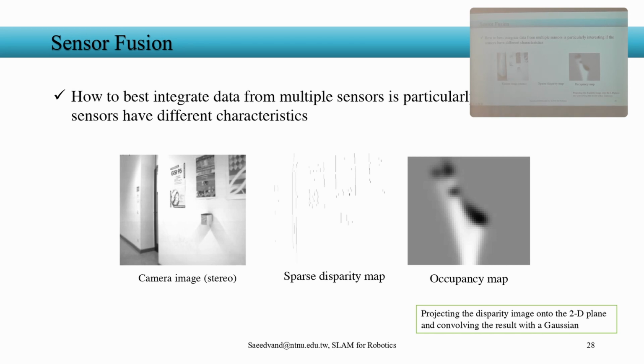So what does it mean? It means that you have two different kinds of sensors, and you need to accurately understand them together to increase the accuracy of the detection. This integration can come not only from visual information, but can also come from the IMU, for example. What is the tilt of your robot? What is the tilt of the camera in order to scan the environment?